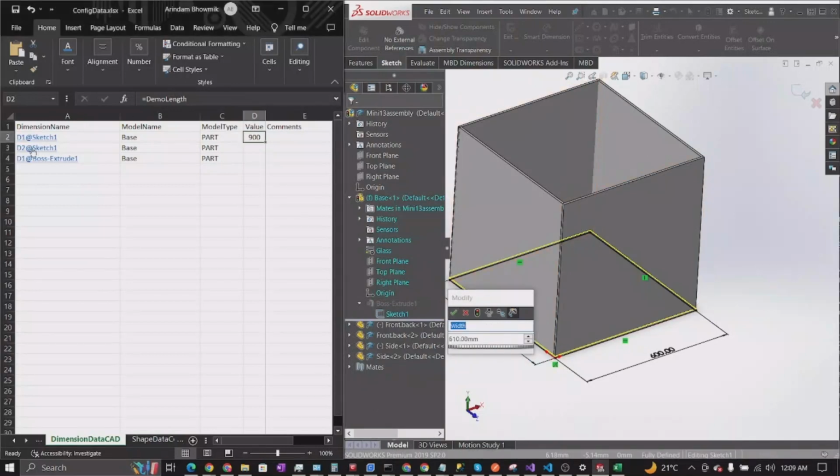If this is a width, then I need to replace this d2 with the width value. How is this width going to be calculated? It should come from the demo width cell that we created earlier. So let's click on that and the value came. Now d1 boss, okay, now we configured the sketch.